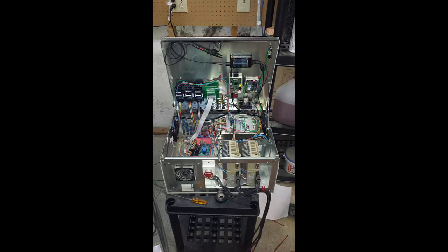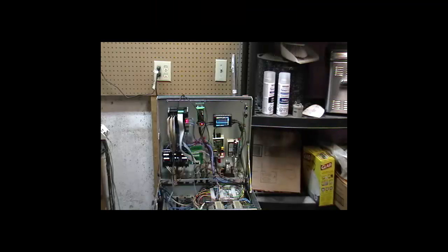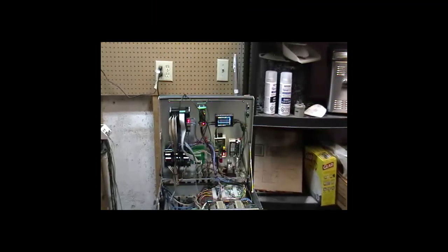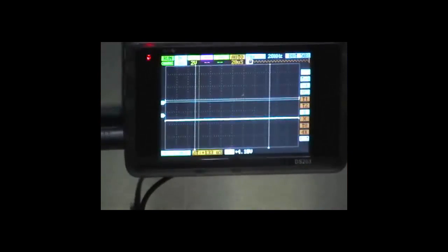So this is what my control looks like now that it's been rewired. You can see in the photograph there is a PoKeys 57 CNC, but there's an oscilloscope attached in the upper right hand corner of the cover above a Raspberry Pi and an Arduino. Let's take a look at that scope during shooting, and we'll be able to see the firing sequence itself. So this is what my system looks like as it comes up. So let's zoom in on the scope, and we'll be able to see now there's a couple spurious pulses that just went by. We're looking for the source of those now.